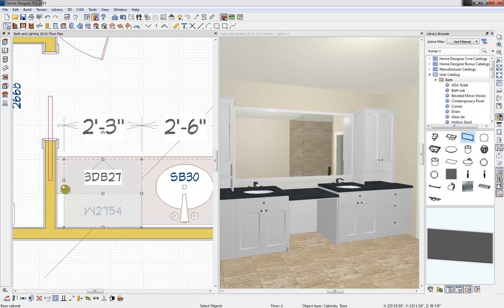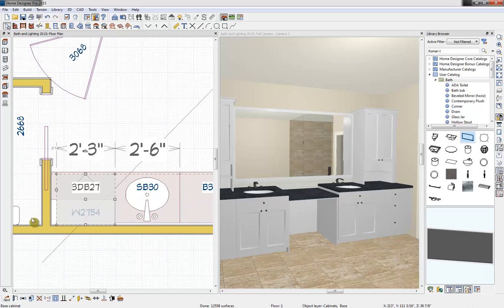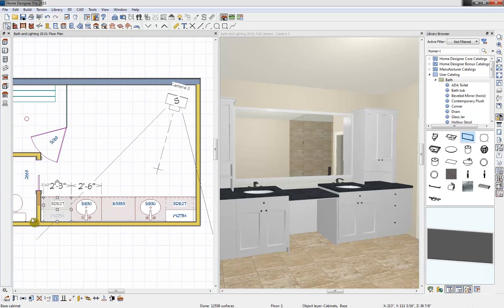So the automatic filler, you'll notice, is 2.5 inches here. If you're 3 inches or less, it's going to automatically place that in there for you. So it's pretty nice that it will just do it for you. You don't have to really think about it, and then you're all set and everything is spaced correctly and no more gaps.